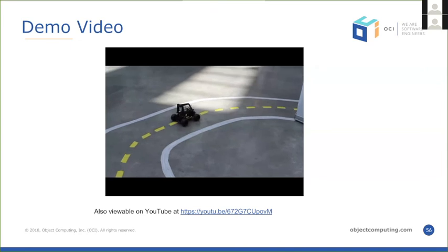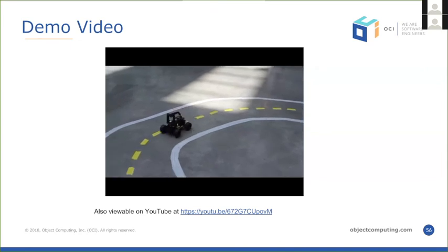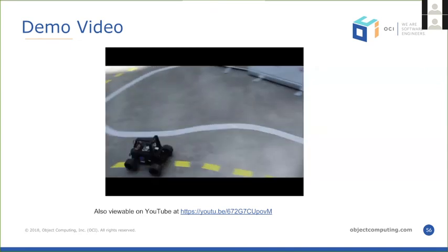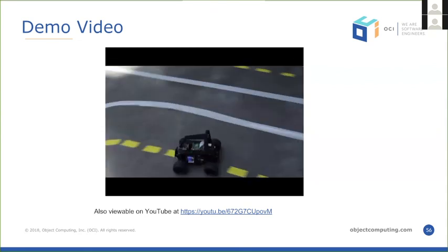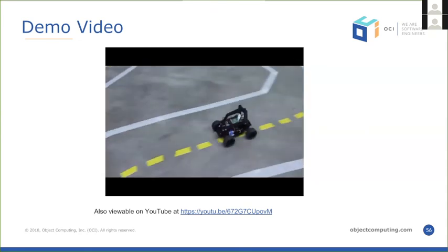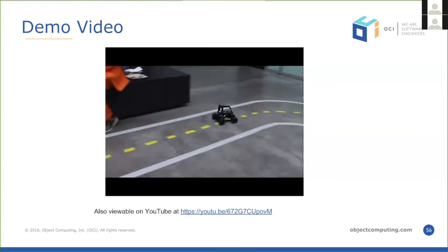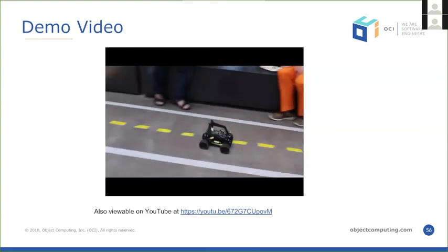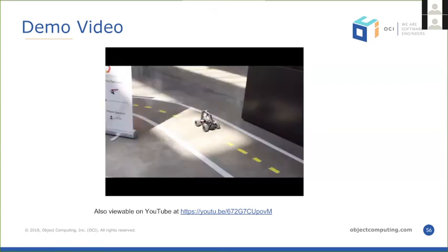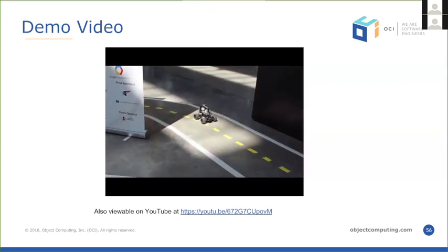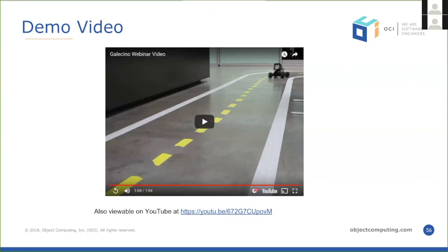And then here's the problem that we run into. I'll show you at the very end of this. This is why lighting is important. So they had a lot of direct sunlight coming in from above. So when it hits that, it blinds the camera. So the camera is basically seeing nothing but white at that point. So then it can't go forwards and it just stops.